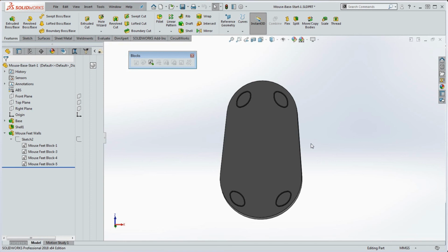So that gives you a brief tour of some of the advantages of using sketch blocks. It allows you to take those sketch blocks and put those into a model that might have angular dimensions to it. It allows it to be fully defined, and it comes together as one big sketch entity that you could easily mirror from one side to the other. So it's really, really convenient using sketch blocks in a manner like this.